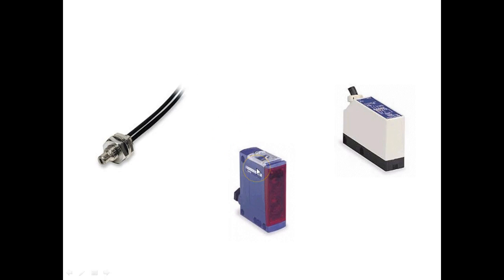You know what attenuation is? Got over distance. So you couldn't run these as far as we could glass fiber, but they work really well in the industry because of what it does: it gives us the ability to put the actual sensing element outside of harm's way. So we might break a fiber cable, but we can replace that and it'll be a lot cheaper than trying to replace the sensor. So on all our fiber over on the lines, the actual sensing element is off away. Except for some of the retroreflectives, the diffuse sensor and the through the beam, they all transmit back to the actual sensing head through the fiber cable.